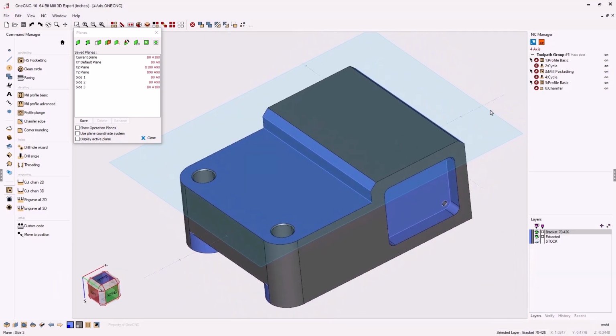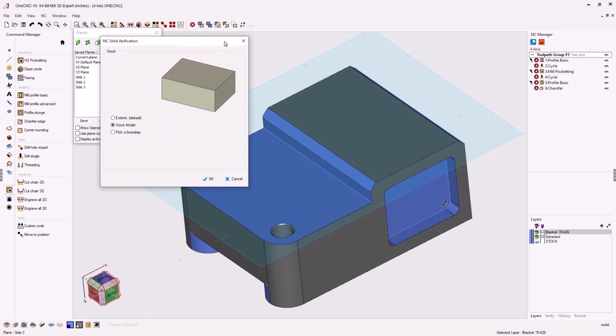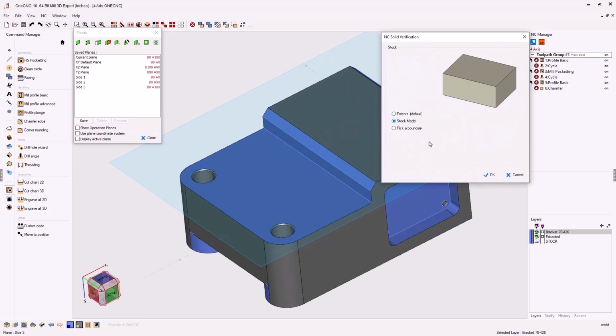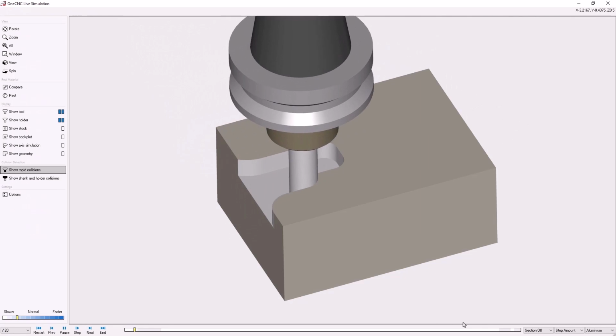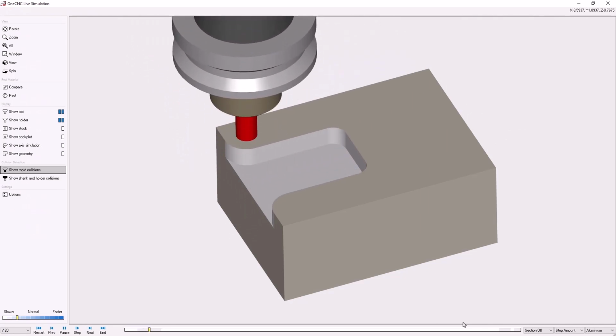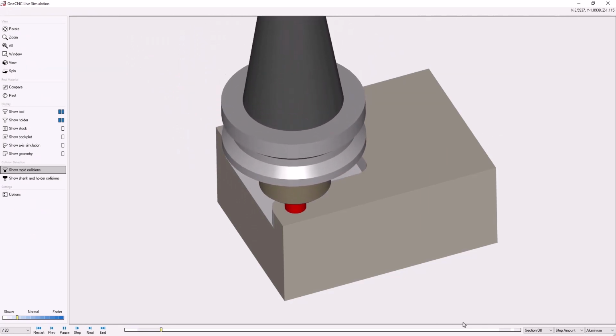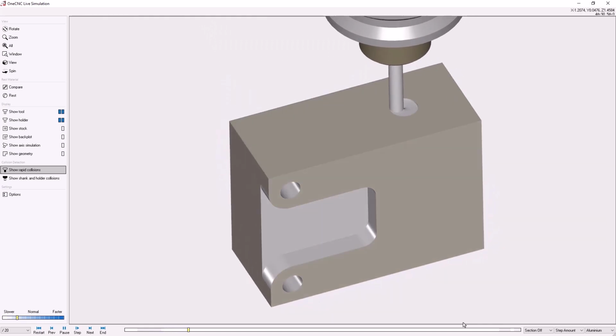So you can see the advantages of using construction planes for each side that you'd like to apply your toolpath to. The construction plane determines the actual amount of degrees that the part's going to index, and it also acts like Z0, so it's very easy to type in your different depths of cut.